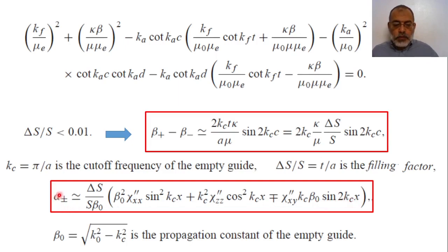This is the attenuation for the forward and backward directions, and it can be noted here that the attenuation coefficient in this case is not equal. So in the forward direction, maybe I have less attenuation than in the backward direction, and this property is quite useful in a very important microwave component, which is called the microwave isolator. A microwave isolator is a two-port network which allows the electromagnetic wave to move from port 1 to port 2 with minimum attenuation. On the other hand, it moves from port 2 to port 1 with very high attenuation. This is called an isolator, and the non-reciprocity in the waveguide loaded by a ferrite slab makes this configuration quite suitable to introduce a microwave isolator, which will be discussed in a following video.